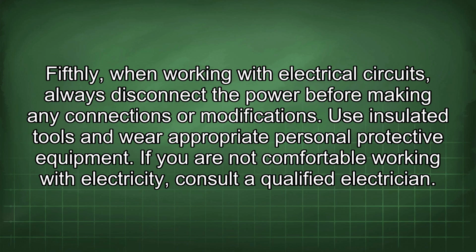Fifthly, when working with electrical circuits, always disconnect the power before making any connections or modifications. Use insulated tools and wear appropriate personal protective equipment. If you are not comfortable working with electricity, consult a qualified electrician.